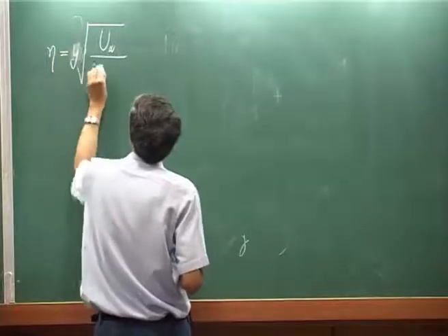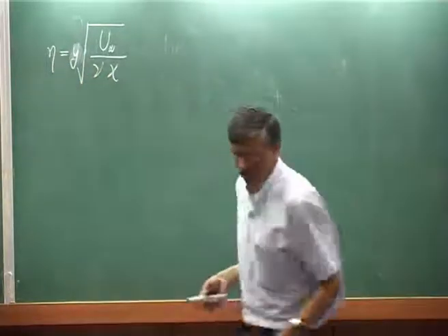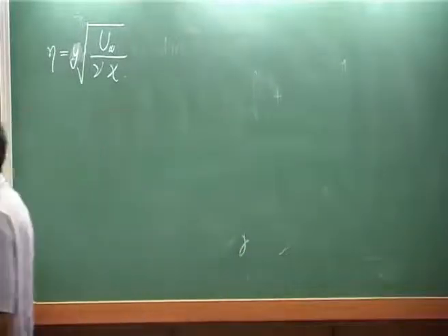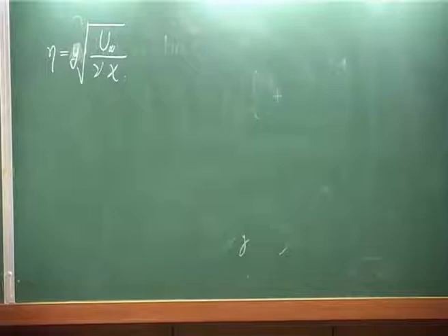So, what is the idea? The idea is the same as what we did with the spring mass system. Wherever we have a problem, we stretch the coordinate. The same thing, if a boundary layer is forming very close to the wall for very small thickness of y, you stretch it open, and that stretching is achieved through this.